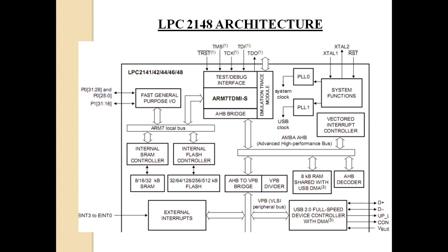Then after a few years, so here what is the problem? You need to have a separate UV eraser for erasing the program, and it will take around 20 minutes for erasing that EPROM. And since UV is a heat radiation, maximum you can perform only 1000 erase cycles. So only 1000 erase cycles can be performed. An external additional eraser is required. And 20 minutes it will take.